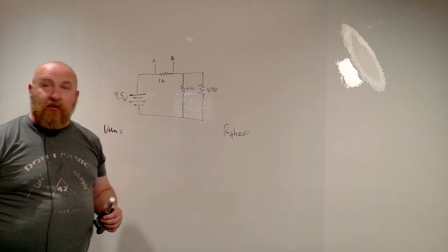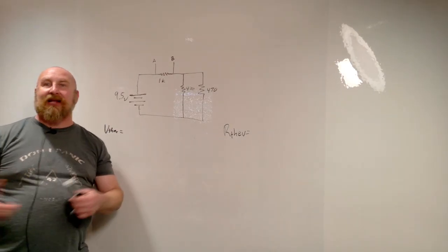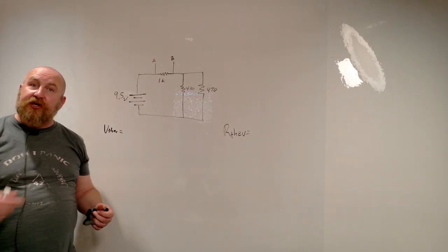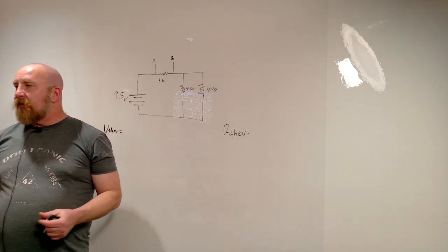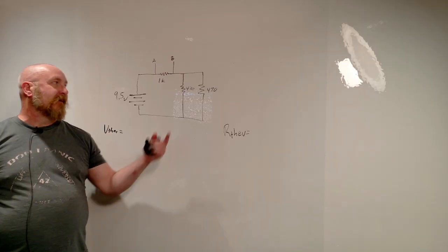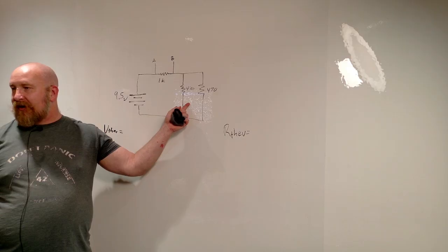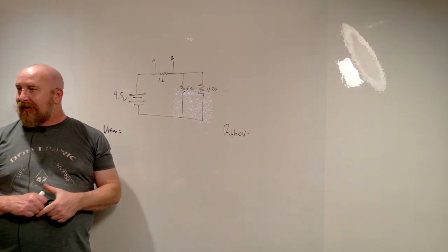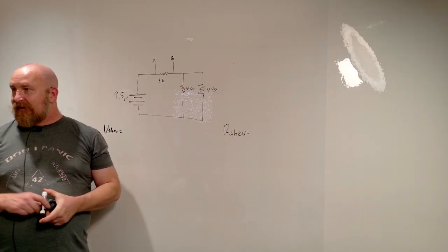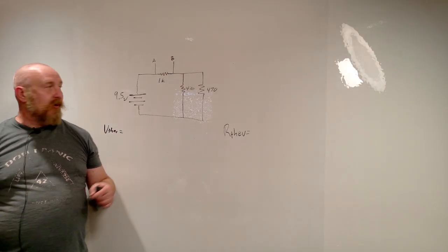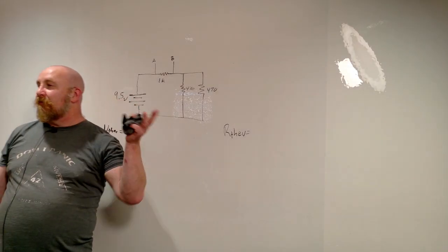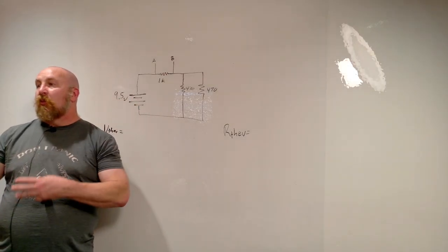So there's many reasons why we aren't going to get exactly the same number, but we should get in the ballpark. And in the ballpark should be determined by our plus and minus range. Those all have the gold band on them, so they're plus or minus 5%, I think. So if we get within plus or minus 5% of the answer, we'll have done good work.